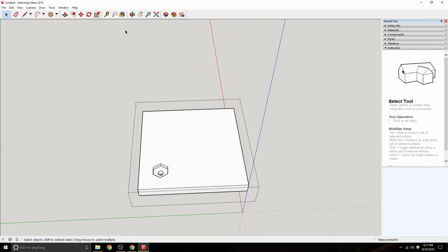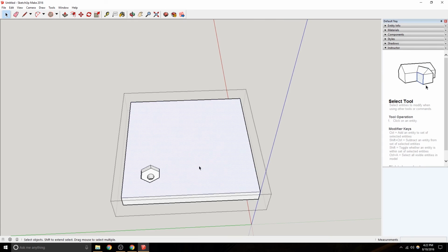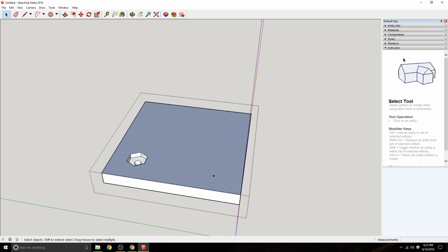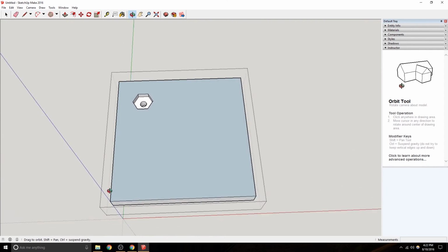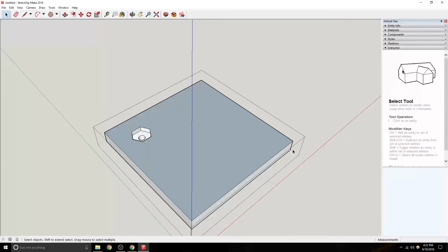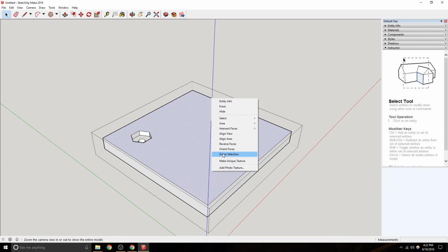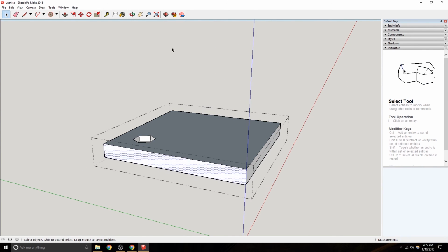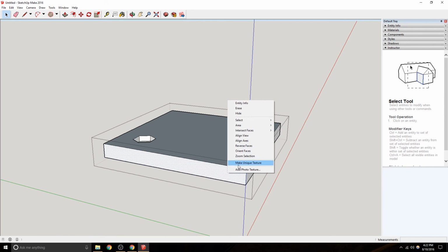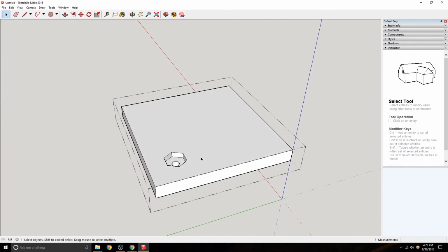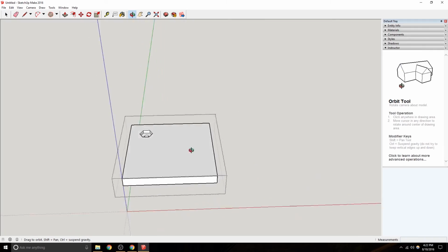So that's a quick way to make parts. There's also a few other really neat tools you can use. Oh, I got to show you faces. If you're 3D modeling this for a 3D printer, like I was saying, there's an inside and outside to a face. Sometimes your faces will be dark where they're not supposed to be because of strange intersection of faces and whatnot. You can reverse the face, or let's say there's a bunch of them that are all wrong. We'll pick one that's right and say orient faces, and it'll turn all the wrong ones to the same orientation. Now that doesn't always solve it if you've got a lot of problems in your model, but it may help.